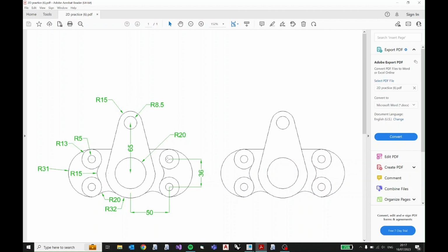The next thing I'm going to do is make these two circles, but you can also notice that these circles lie along either side of this horizontal line. So I can make only one circle and then mirror it on the other side as well. So I'm only going to make these two concentric circles.